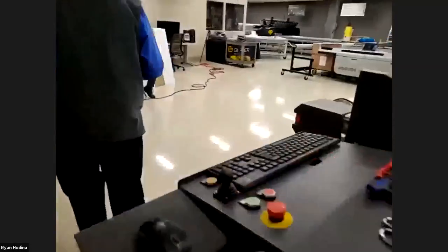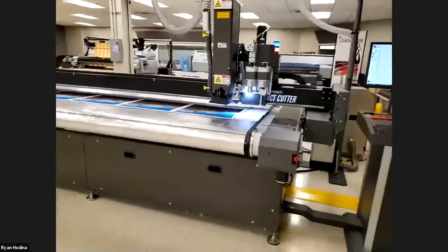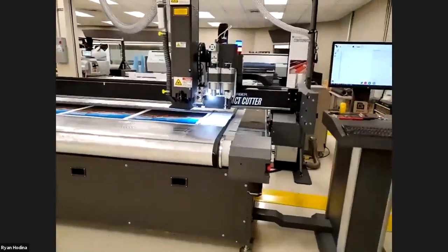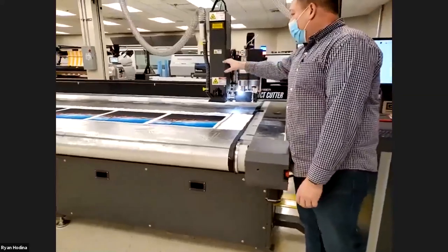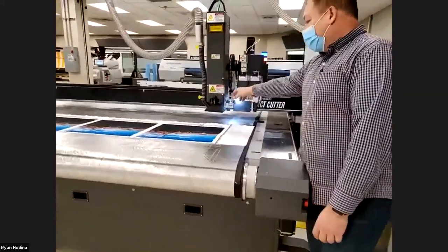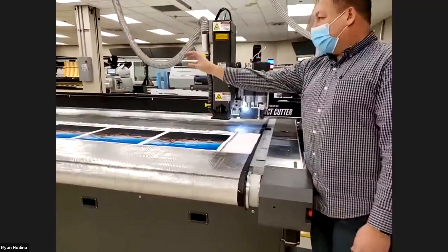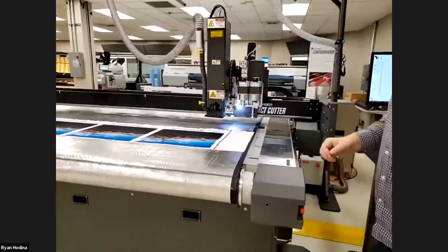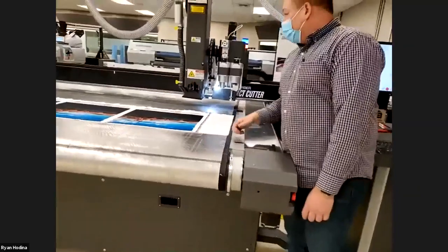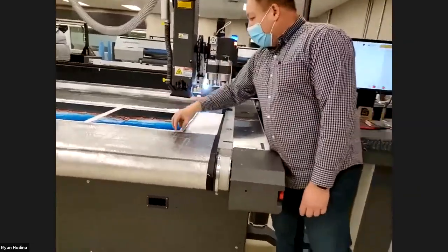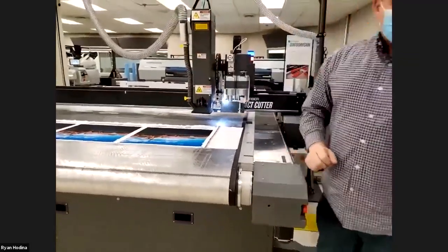So I think, Greg, you want to show the capability of the laser? Certainly. Okay. So let me move this out of the way for a second. So as Mark mentioned a couple minutes ago, we're going to do a cut with the laser, and we're also going to go ahead and use the camera for the registration part of it. So that'll make sure that the laser cut is going to be matched up, in this case with the printed graphics, correctly. So you can see here we've got black registration dots around each one of our cuts. So the system is going to go ahead and use the camera and find the dots for each cut. Go ahead and make that cut, and then move on to the next one.